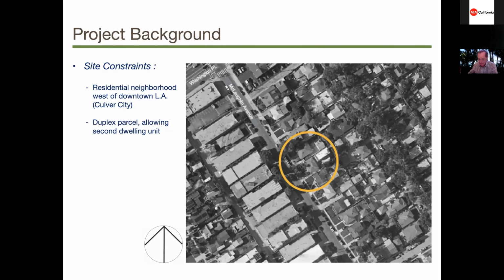I'll just use this Google view. There's a tree right here, which shades this a little bit in the midwinter months at midday or in the morning. You can see due south, the sun gets through just fine. But in the early morning hours in December, you get some sun on the collectors. That tree is in the neighbor's backyard.